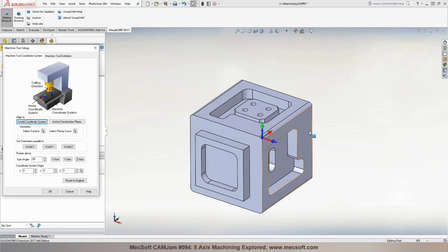Okay. Because I think that is used at some moment for 4-axis programming when you want to use the turning feature. Is that correct? When you do 4-axis programming, you're going to do rotate table setups rather than using this machine setup. Yes. And you specify the rotation angle about the axis of rotation that you've defined.